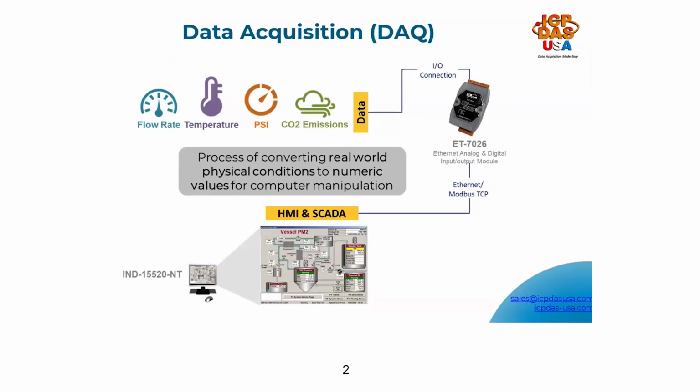The ET7026 acts as a Modbus TCP server to the AVEVA Edge software, which is the client. The ET7026 has 4 I/O types: AI, AO, DI, and DO. Connecting all 4 are very similar. I will show you this in the next few steps.